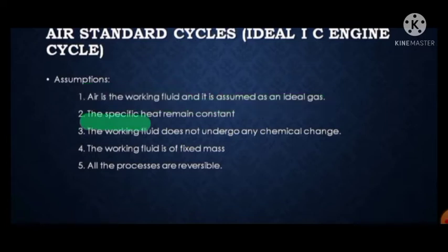Then the specific heat remains constant. The specific heat at constant pressure as well as the specific heat at constant volume remain constant. You all must know that as the temperature goes on increasing, there is a change in specific heat Cp as well as Cv. But in an IC engine, we consider them to remain constant. So the first assumption was air is the working fluid, so that we can use our ideal gas equation, and the second is that the specific heat remains constant.